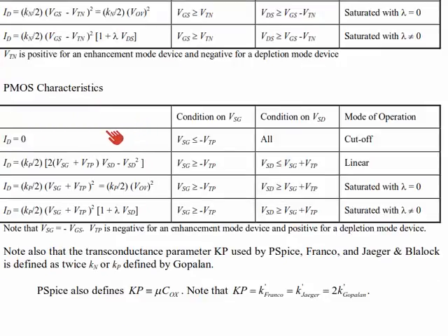For PMOS transistors, the situation operates very similarly, but as you know, PMOS transistors have holes. Forming a channel to attract holes needs a negative gate-to-source voltage. So I find it simpler just to switch the subscripts. VGS negative means VSG positive.